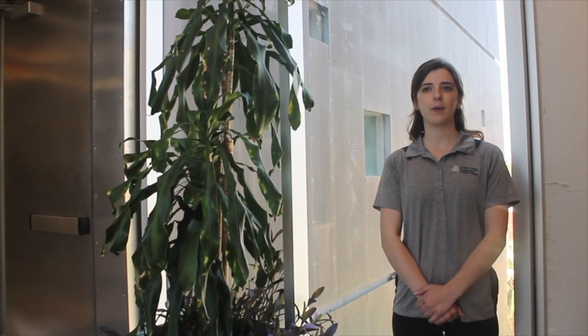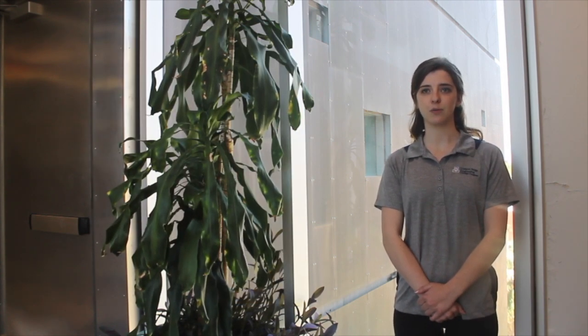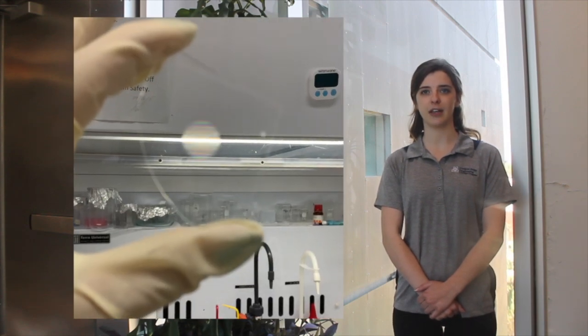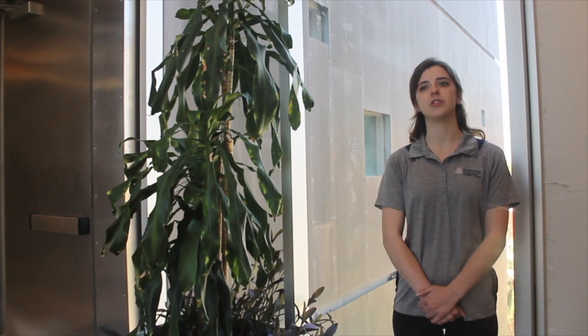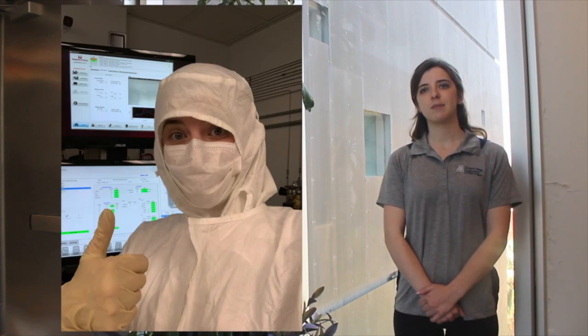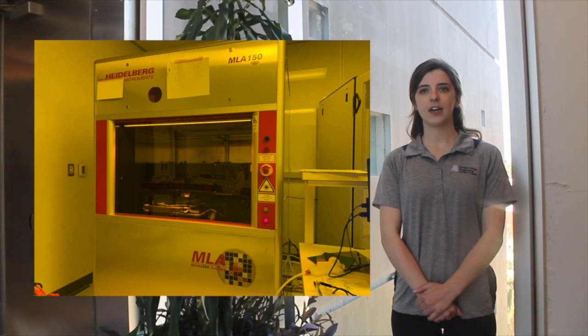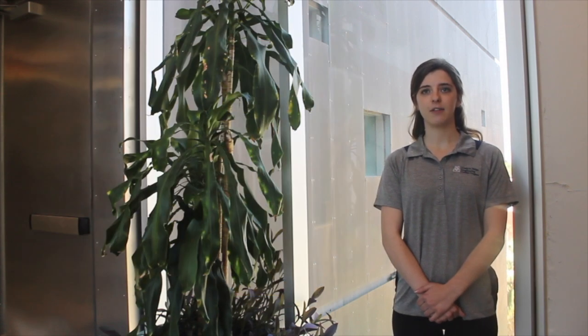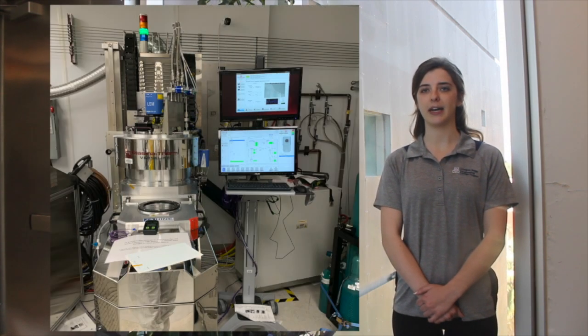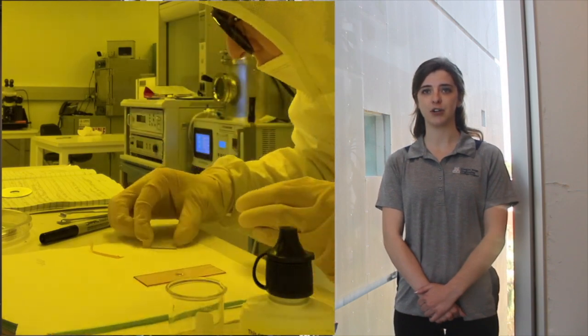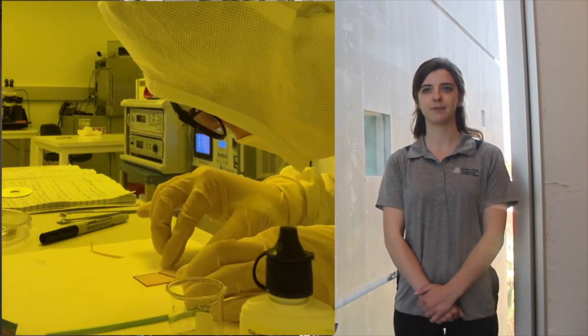One major issue we ran into during the integration process was acquiring the diffractive Fresnel lens. The original manufacturers hired to make the design were unable to do so. So one of our optical team members went through the training required to make a binary prototype and final calibrated grayscale DFL. This process involved both binary and grayscale maskless lithography, fused silica plasma etching for the binary prototype, and UV resin cured stamping for the grayscale optic.